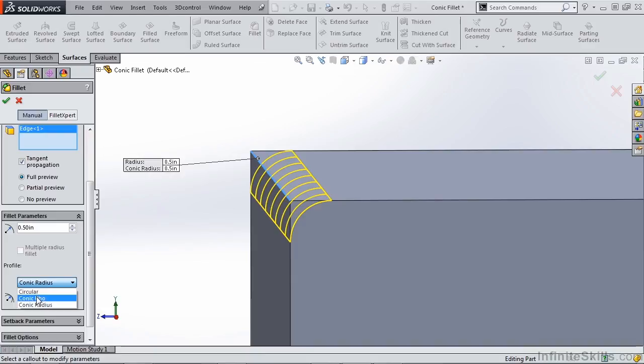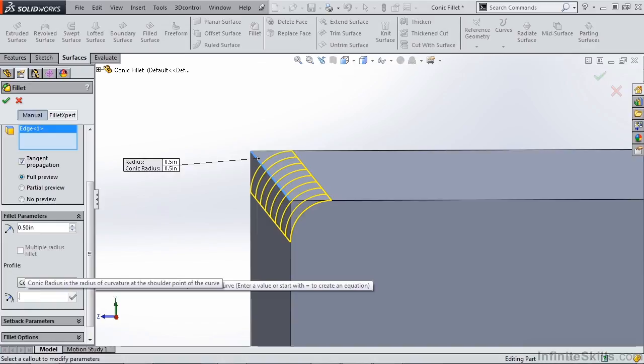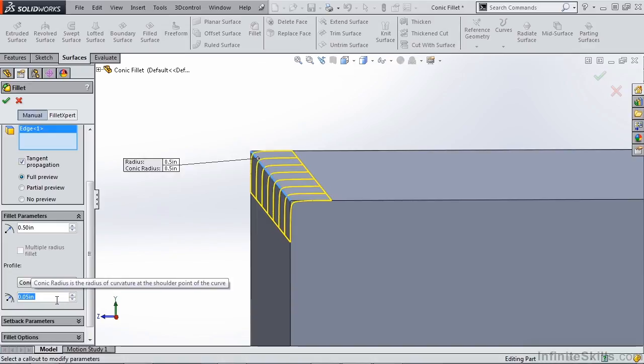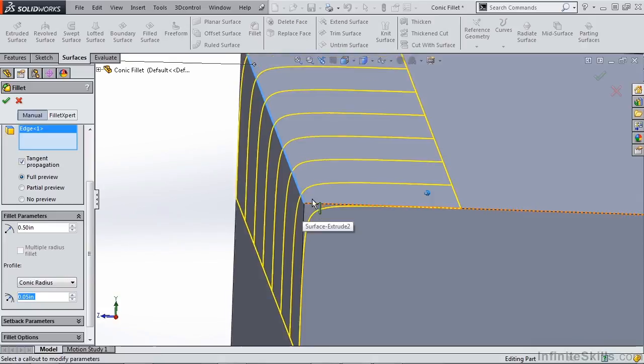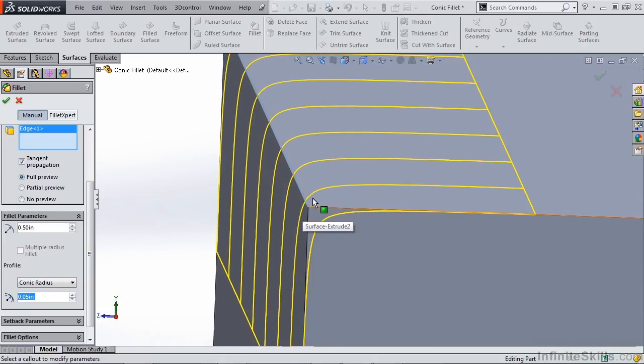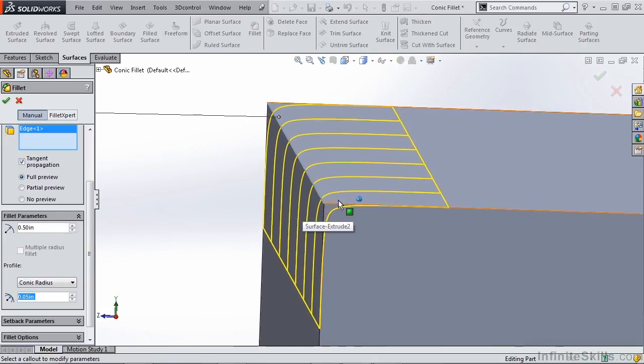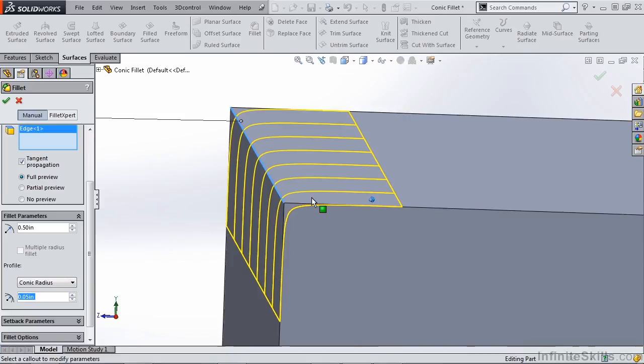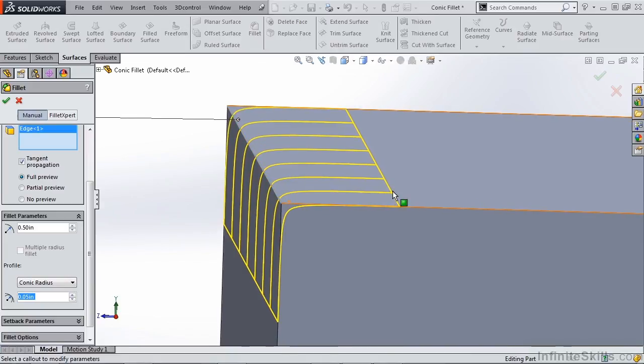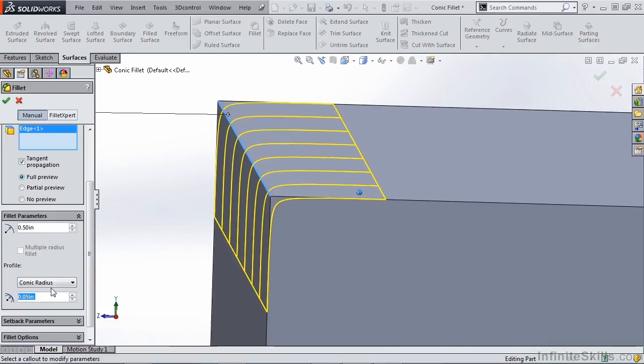And we also have the same type of fillet as conic rho when conic rho value is set to 0.5. If we set this value lower, like say 0.05, then what we're telling it is the radius of curvature in this corner, in this shoulder point, is much smaller. So again, this is like the conic rho in the fact that if you set conic rho to 0.95, a very high value, you get much more weight, much more interaction between the surrounding surface,